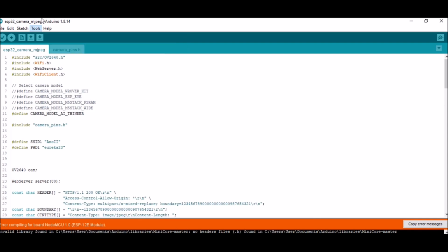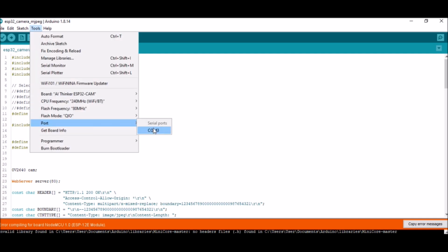Let us talk about possible problems that may arise in the course of this. 1. If you are using the ESP32 CAM USB programmer, the USB port you selected may not be the right one. The best way to resolve this is to remove your USB from your programmer. Check the available ports without it. Insert the programmer again into the USB, see if there is an additional new port address. Select this as your USB address programming port.